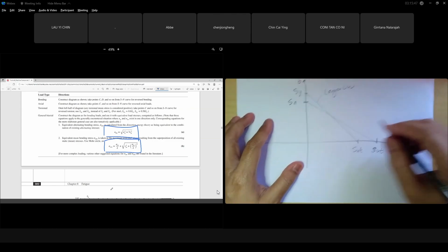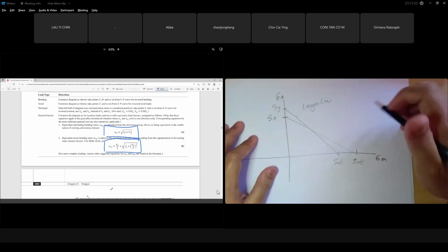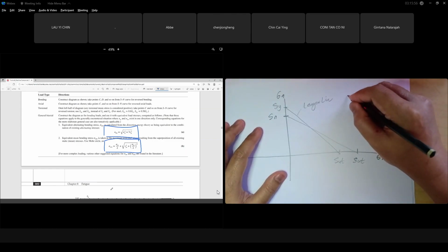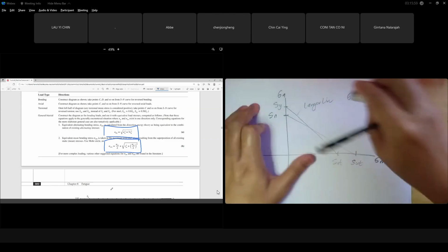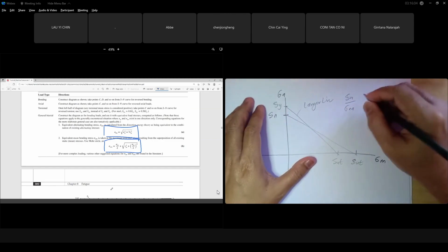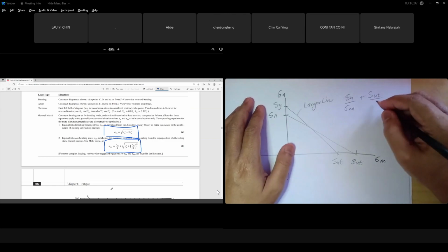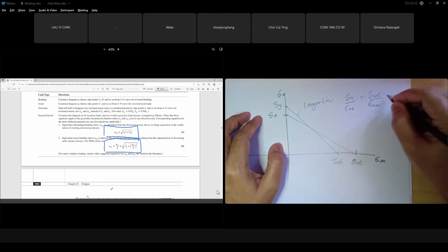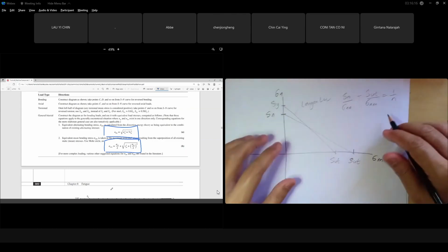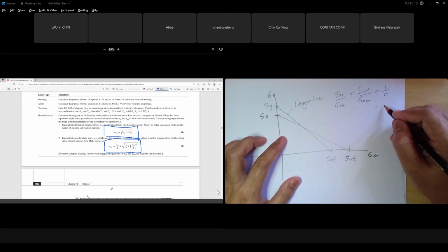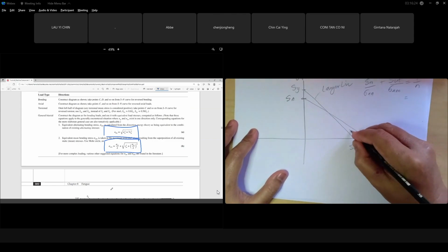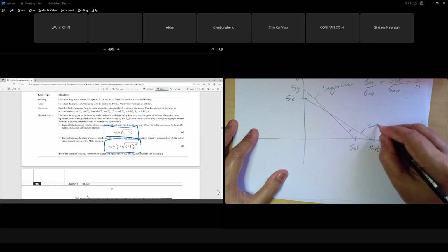Because sometimes when you plot, if you don't use the graph and you just use the equation, you get your Sn over sigma EA plus your SUT over sigma E mean equal to 1 over your safety factor, right? You just calculate your safety factor, you get 1.2, safe. But your point sometimes does look safe because this is your Goodman line. Your point is here. It is safe because this is the Goodman line. It looks safe on Goodman.